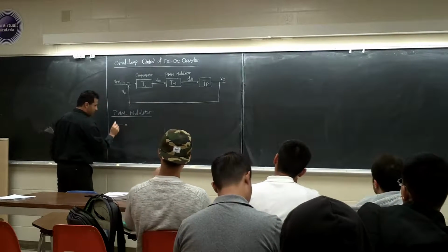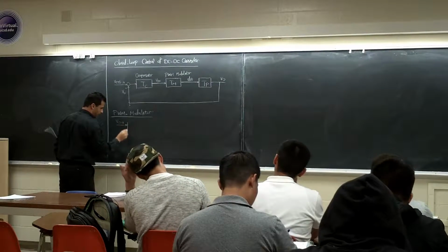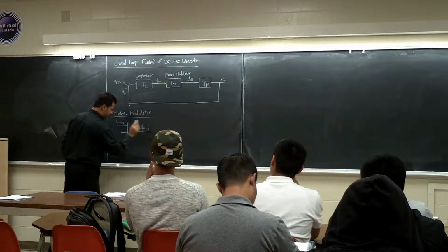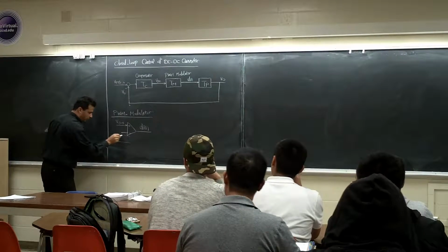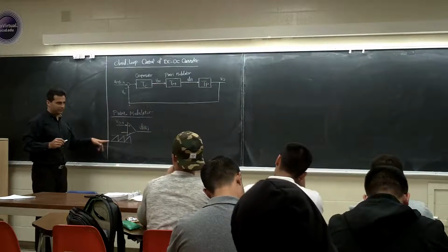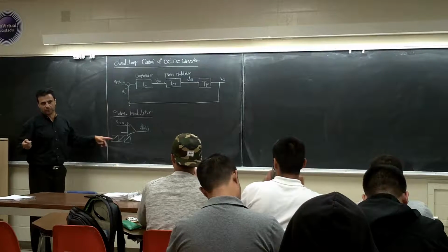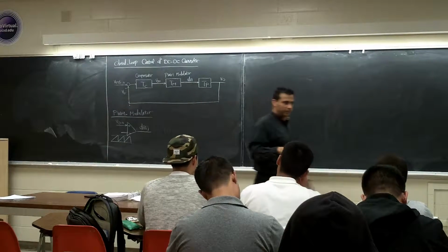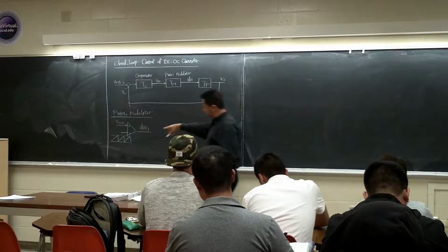Basically, a V control is going to come in. V control is going to come in. Compare with a sawtooth. You can select the same thing we had before, but this is easier. Right? So you have a sawtooth. The frequency of this one could be 20 kilohertz, 10 kilohertz, 100 kilohertz. This is the high frequency, like the PWM signal we had, right? The triangular with the frequency was like 10 kilohertz, 6 kilohertz, whatever. So this one has a high frequency.